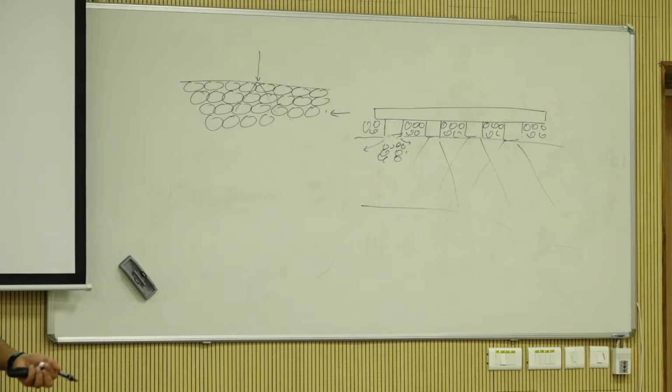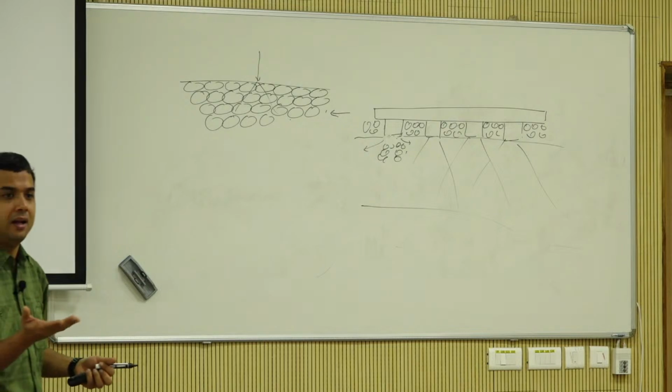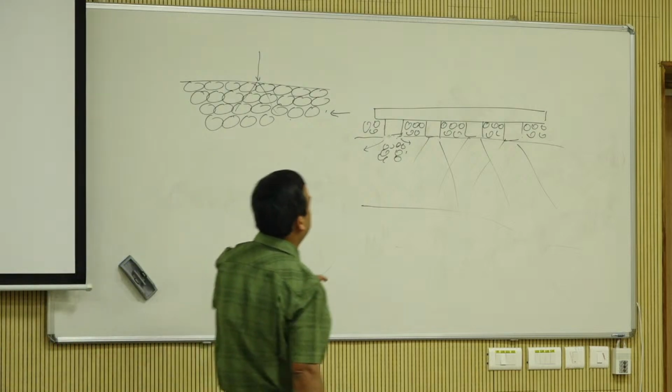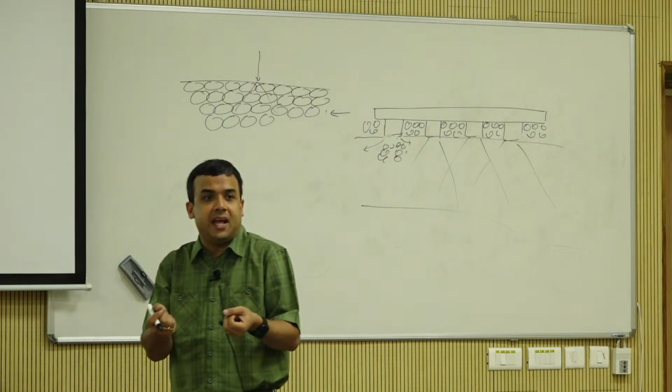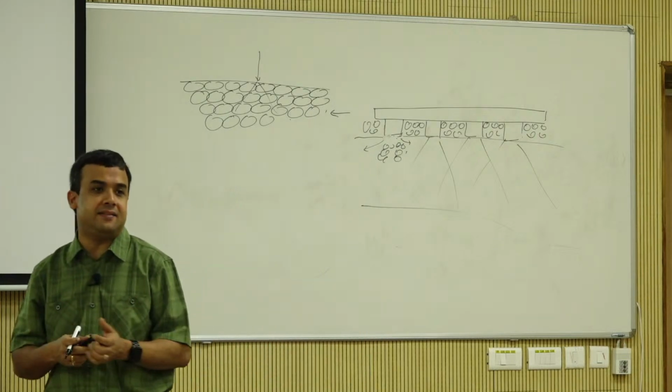It's connected to the rail, right? It's hanging from the rail. It's not just sitting on the ballast. It's clipped to the rail, so the clip is going to hold it up. And the rail has a pretty strong bending stiffness.